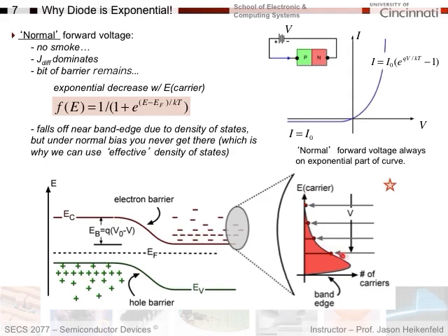So you never get to the point where you run out of more electrons that can go across, because this is already biasing the diode. When you get to this point, you're already biasing the diode much more strongly than it can handle thermally, and before it basically turns into a puff of smoke. And so you'll never get to the point where you can start to see that the density of states decreases the available number of electrons.